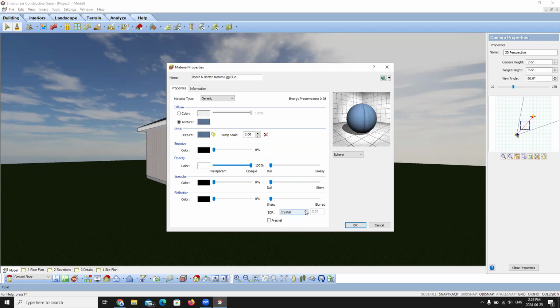These are preset values. You can also do a search online if you wanted to for index of refraction, and it will give you the different codes that you can enter in manually. To do that, you would select custom, and then you can type in whatever value that you want. I'm going to keep mine set to air, and we're just going to say OK to that.